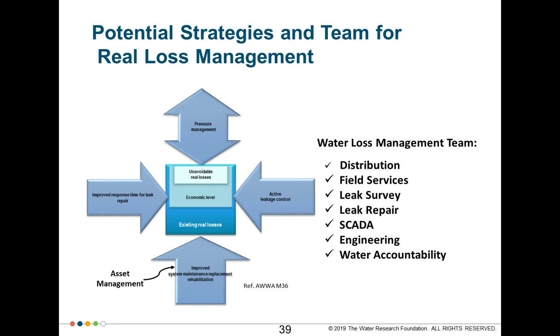In some distribution systems or portions of systems, proactive pressure management may be found cost-effective while maintaining desired levels of service and water quality. The fourth pillar is a long-term asset management practice involving rehabilitation or replacement of mains, services,